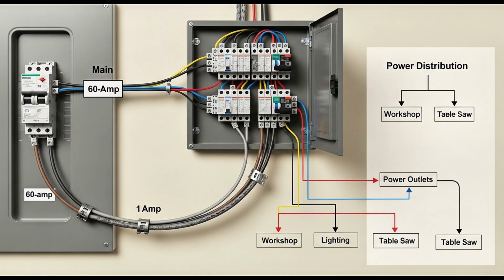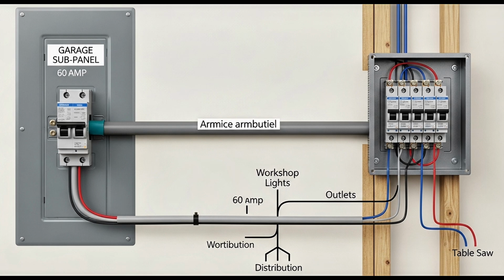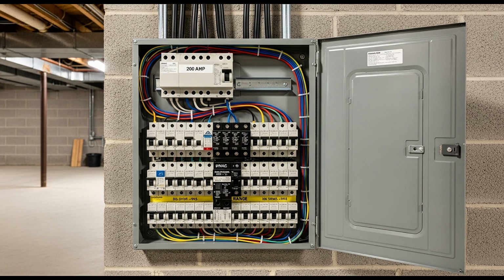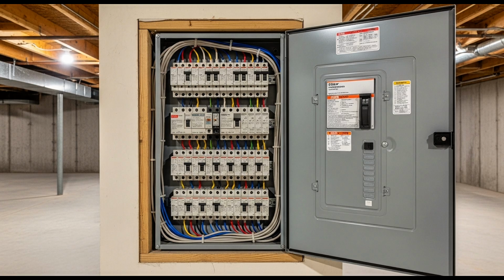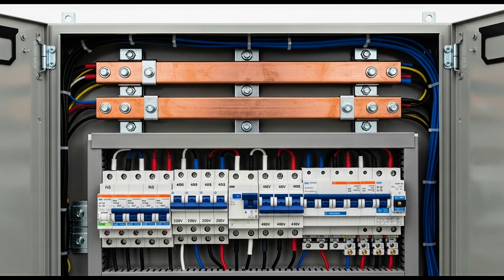This wire runs through the walls to serve multiple outlets or fixtures in what we call a home run, the path from panel to the first outlet, then daisy-chained to subsequent devices. At each outlet or light, the hot wire connects to the device. When you plug something in or flip a light switch, you complete the circuit. Current flows through the device, doing work, heating a coil, spinning a motor, or illuminating a filament, and then returns through the neutral wire. All the neutral wires from the various branch circuits return to the panel and connect to the neutral bar.